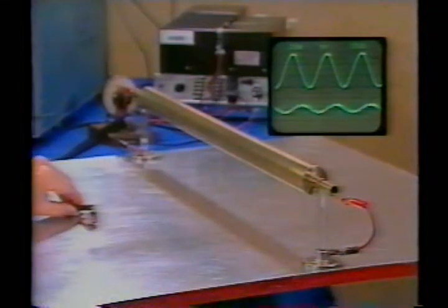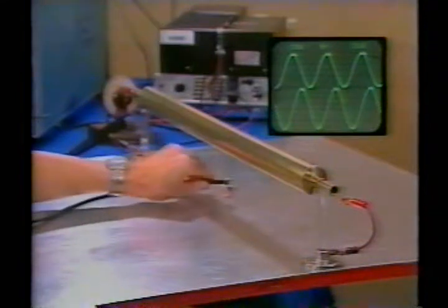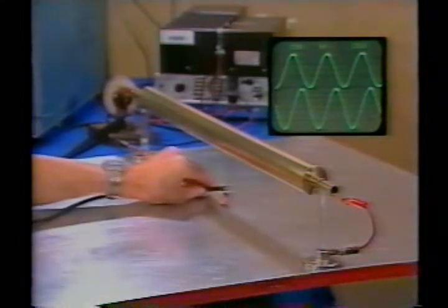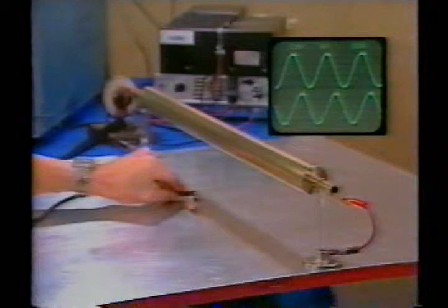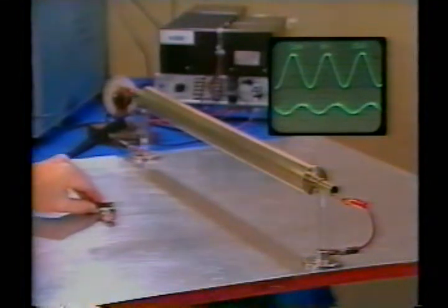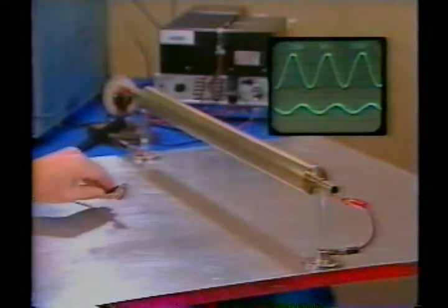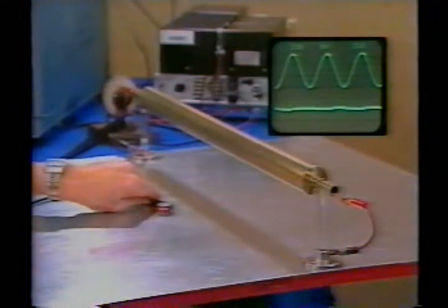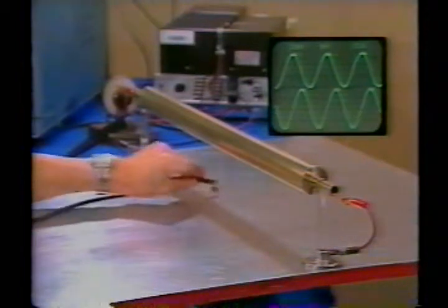Our theory predicts the flux density at the center line, where y equals 0. Our current is 3 amps. The conductor height is 11 centimeters, and its radius is 2.1 centimeters. So A is 10.8 centimeters. The predicted flux density is then 0.11 Gauss.